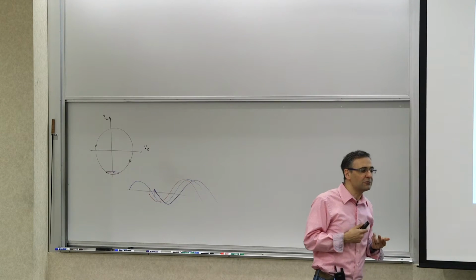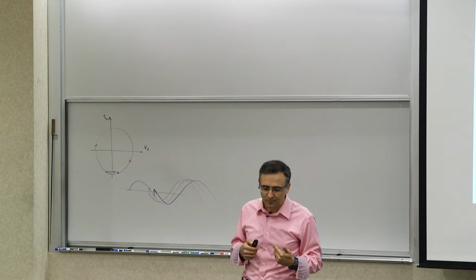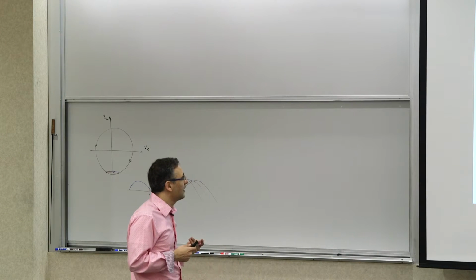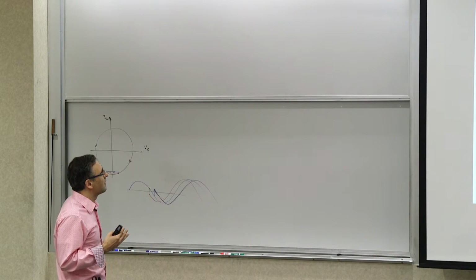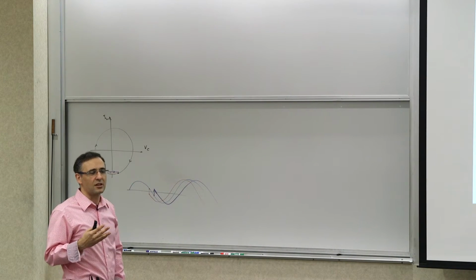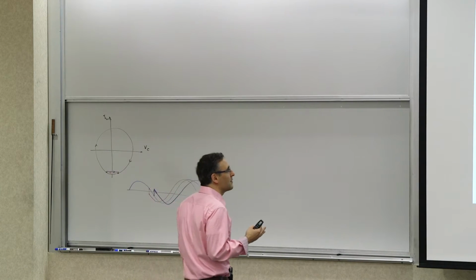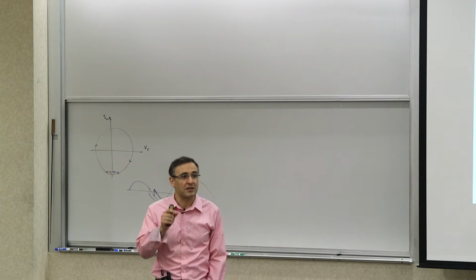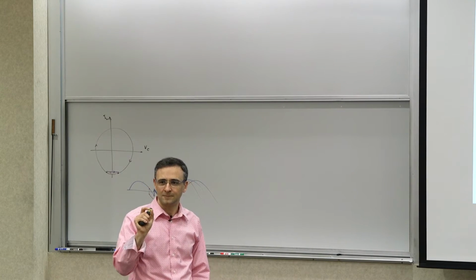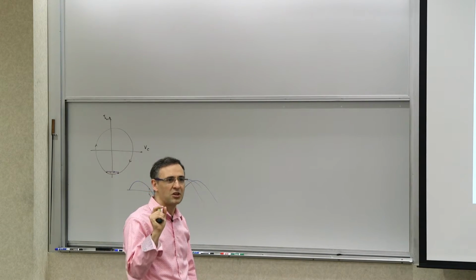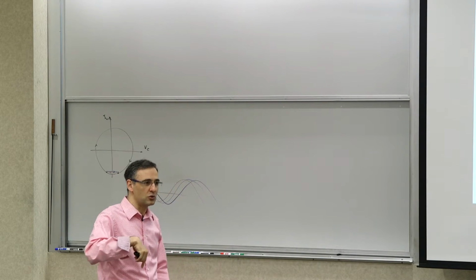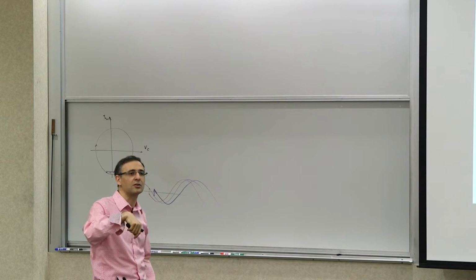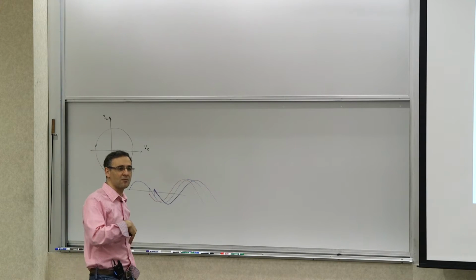Now, the other interesting question related to this is the effect of the number of stages on the ISF in a ring oscillator, right? Ring oscillators are convenient to use because they are very small in area. They're very compact. Because usually if you want to make an LC oscillator, you need to have an inductor, and we implement our inductors as spirals, and they become large.